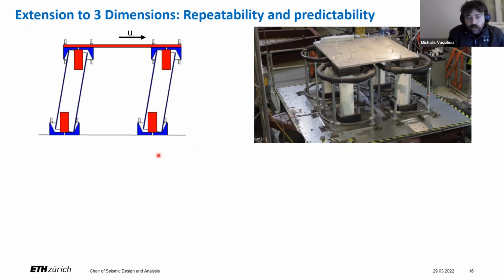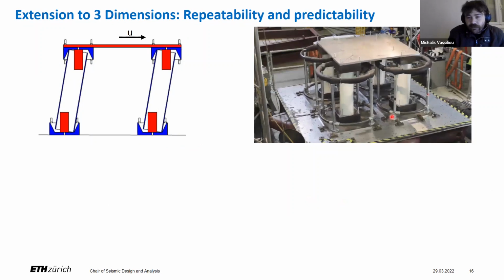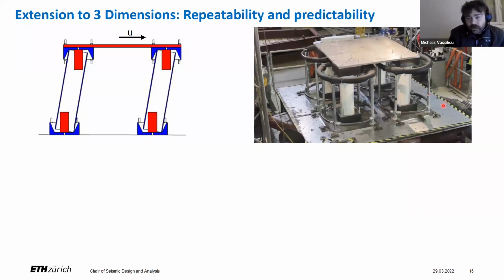So we tested one more conceptual model. Here it is. So here's the model: 4 steel columns with hollow cross sections supporting an aluminum slab. All connections are dry, but we have used these restrainers here, the black ones, shown as blue here, to constrain the columns not to roll out of their original position. We wouldn't want this for a real bridge anyways.